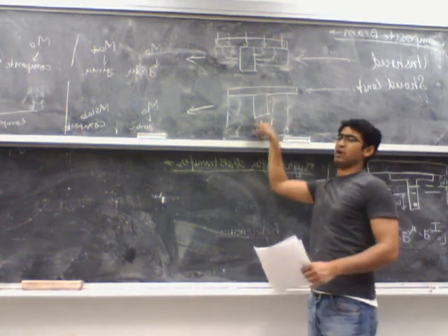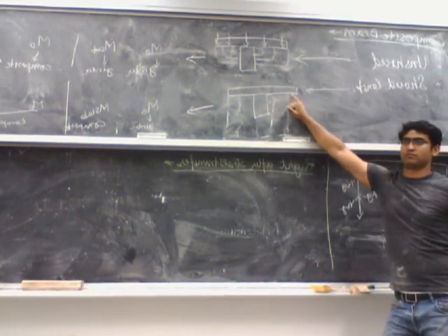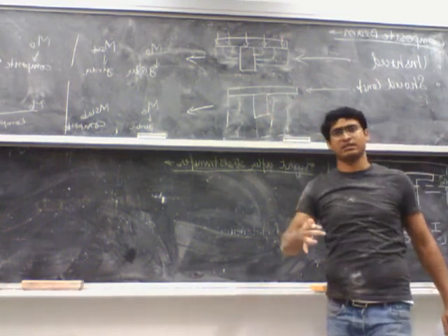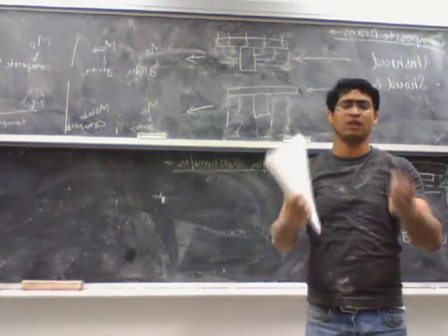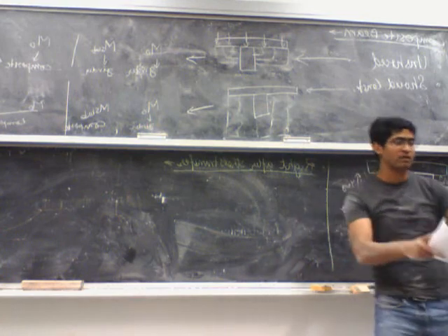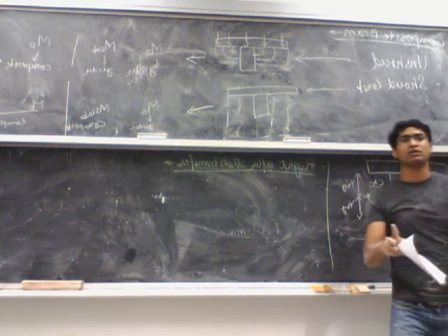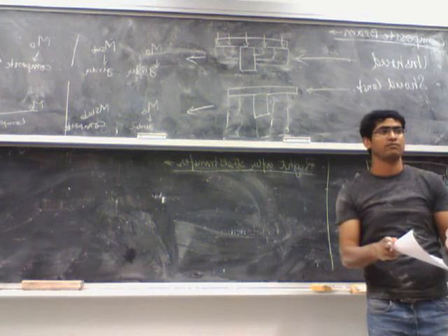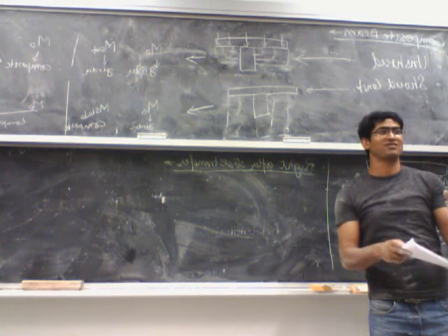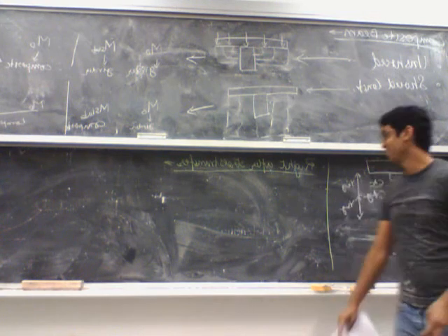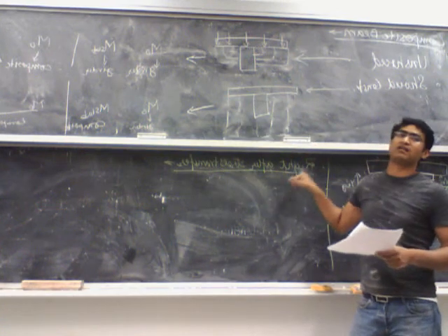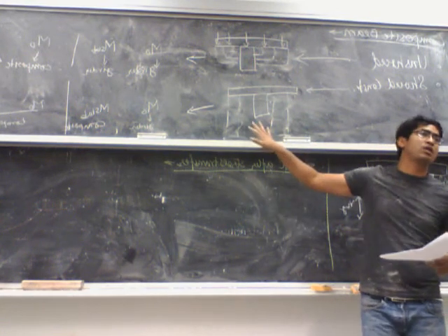In either of these two cases, do I have the slab right after the stress transfer? You construct the girder, you apply the pre-stressing strand before you, of course, cast the girder, and as soon as you cut those tendons, do you have the slab on there? No. So no matter whether you have unshored or shored construction, right after the stress transfer, you don't have the slab at all.